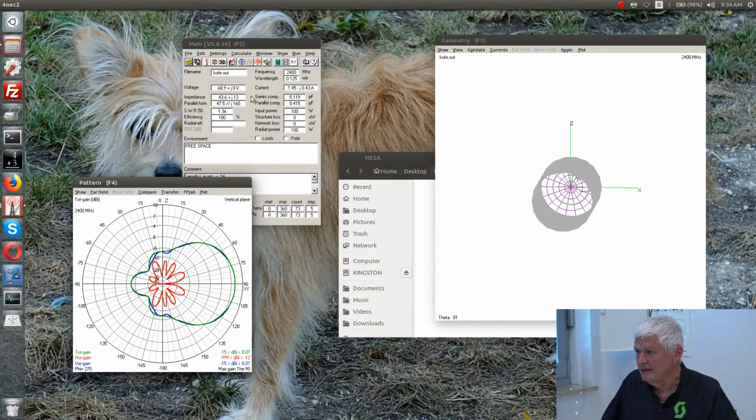You see the impedance, now the reactive part already decreased, but also the real part decreased. The real part is now a little bit off, but the most important thing with the impedance is, we see we change the impedance just by shortening the probe by 2 millimeters. So we solved part of the problem here.